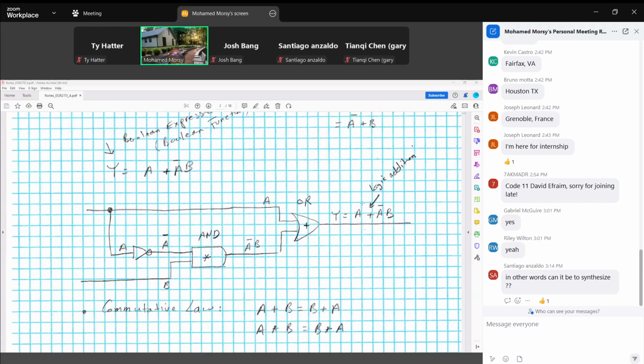And now the two terms are added here. One term is A, plus the other term is A inverted B. And between them is logic addition, plus. So this means if we consider this one input and this the other input, they both are applied to an OR gate.